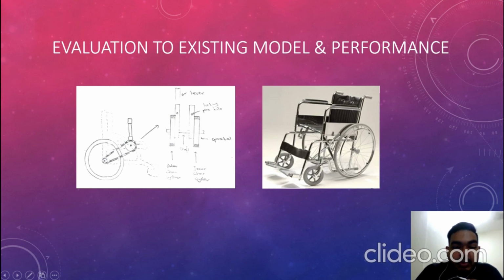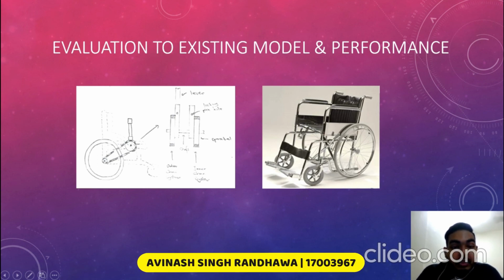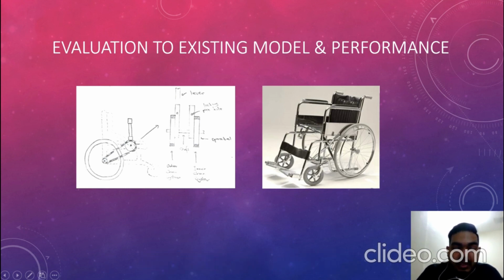At the left shows a wheelchair with a dual chain system on both sides. In order for the wheelchair to move forward, the user must slide the lever and lock in the outer chain system to move front end. In order to reverse, the user has to slide the lever and lock in the inner chain system to move backwards. Comparing with the model on the right hand side, we can see that it shows a manual basic wheelchair which needs more force applied to move.